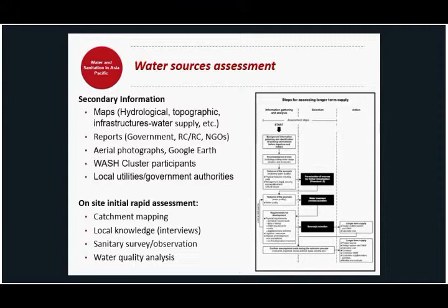And you can also do water quality analysis. This gives a single result for that moment in time. It's indicative without information about all parameters. Some parameters, such as fluoride, will not fluctuate over short periods of time, but others can, such as turbidity or fecal contamination. Measurements of turbidity and salinity are often taken with field kits to help decide the applicability of different types of water treatment. We will see that a bit later.